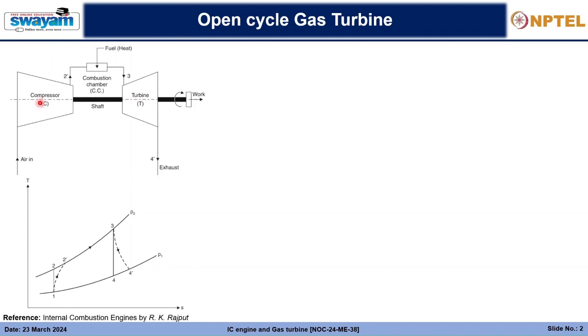In order to compensate for the heat loss, because we need the pressure to rise to a particular value that is constant, we have to apply some extra work to make that pressure difference possible. That's why more work is done in the compressor due to these irreversibilities, and that's why it has to follow the path 1 to 2 dash.